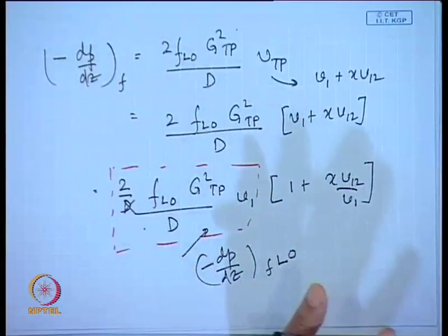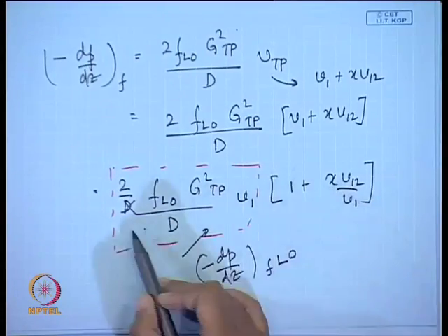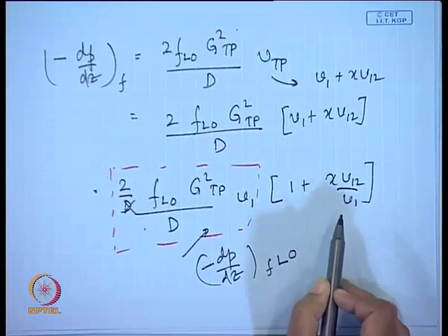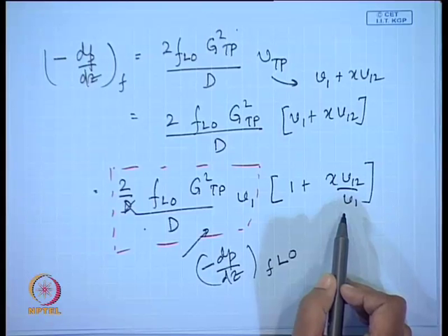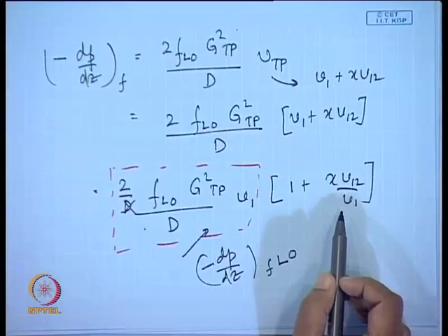This is a very standard thing, that in the two phase mixture, suppose you start from x equal to 0 to x equal to 1, x equal to 0 means it is just liquid flowing, x equal to 1 means it is just gas flowing. Now, if you put x equal to 1 in this particular expression, are you going to get the expression which we would obtain when only gas is flowing through the pipe? Just observe this expression, you are not going to get it, is it not? So, it does not conform to one of the limiting conditions, and that is a very severe limitation. We can use it for only a very specific situation, we cannot extrapolate it by any particular means.